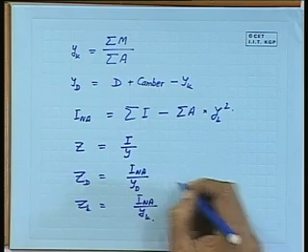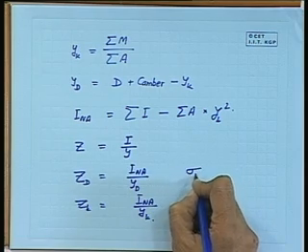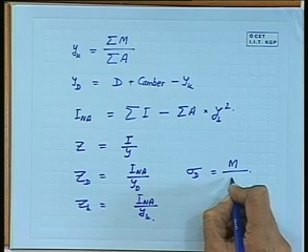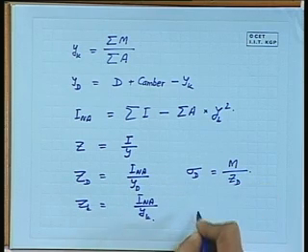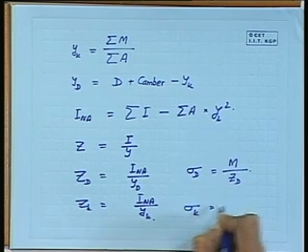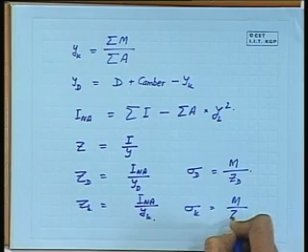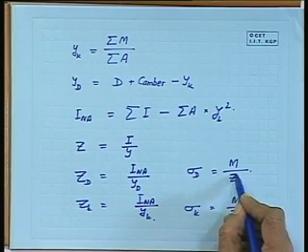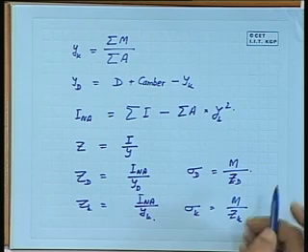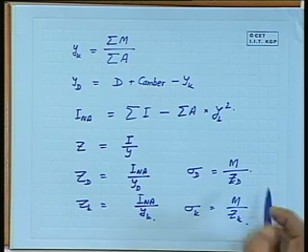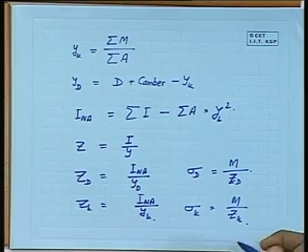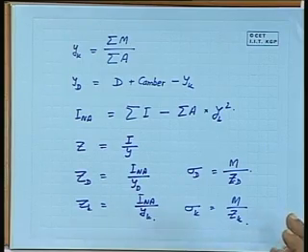Now, after getting these Z values, I can find out sigma at deck is equal to M by Z deck and sigma at keel is equal to M by Z keel. It's okay. So, these two give me the numerical value at any section.